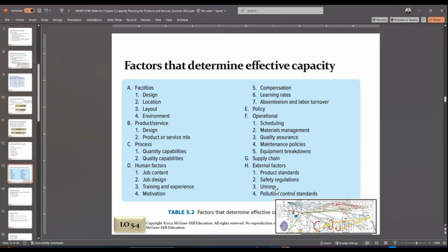All the raw materials come in at the inventory area, get checked in, and then go to the powder mixing area, then powder assembly area, then sintering cube assembly area, then sintering press. So this is a continuous flow. Once the sintering process is done, it comes to finishing: finishing department one, finishing department two, and final finishing department. So again, there was a flow. That's what I'm talking about.